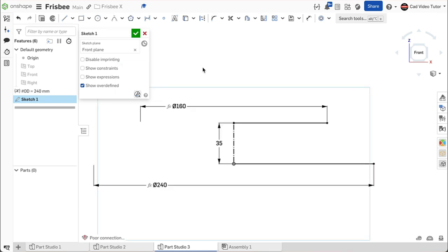Now we can create the conic arc that makes the curve on the outside. From the Sketch toolbar, choose Conic from the Arc drop-down menu. Click coincident to the end of the top line and coincident to the end of the bottom line. Stretch the arc outward and look for a horizontal icon and the row value to be 0.5. Click to set the arc and use Enter to accept the row value.